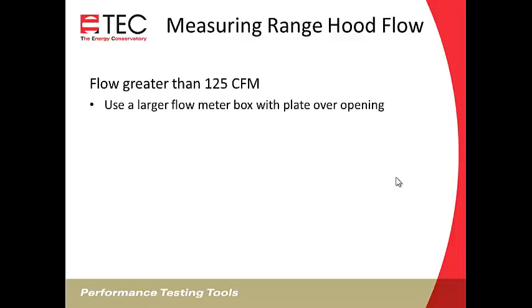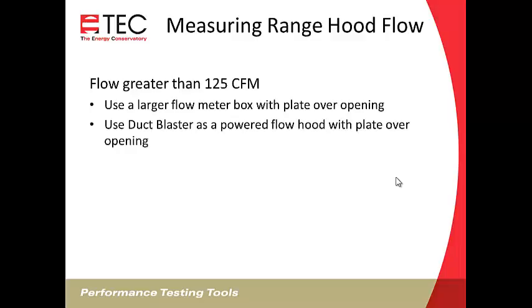We talked about the depth of the exhaust fan flow meter being at least as big as the largest dimension of the opening, to allow that flow to equalize and straighten out before it goes through the hole. It's important to have that aspect when you're measuring flow through a range hood. So you can use a plate to cover the opening, cut a hole in it the size of the flow box you're using, and get a measurement that way.